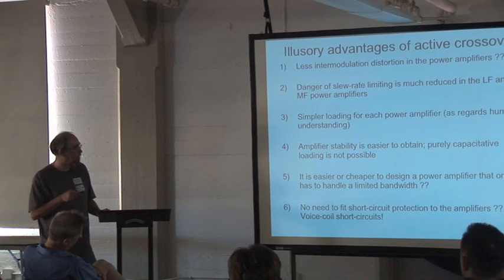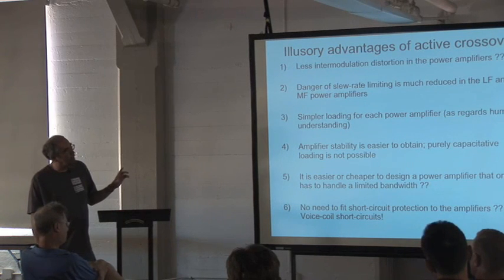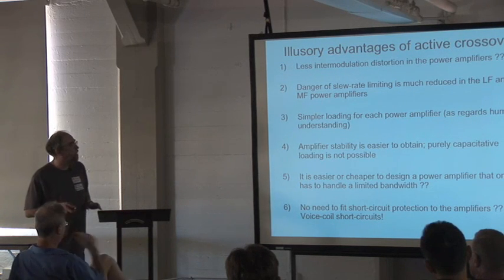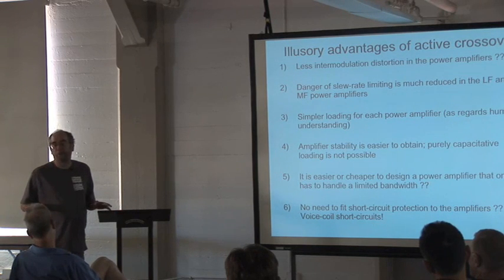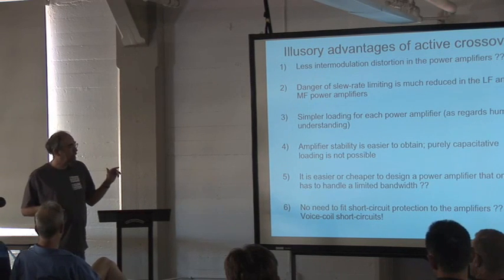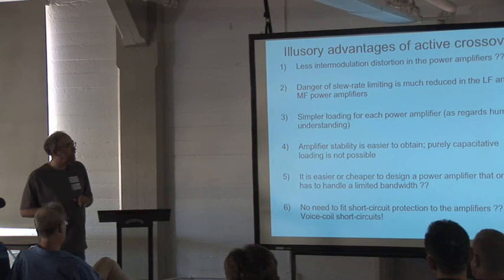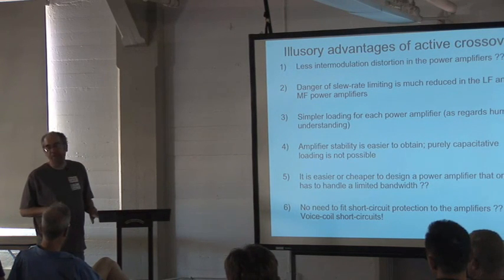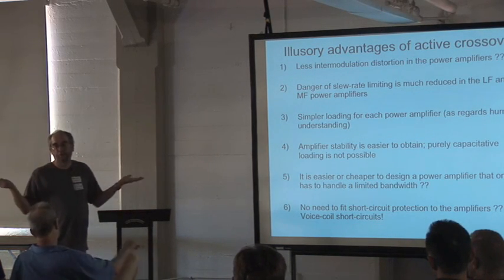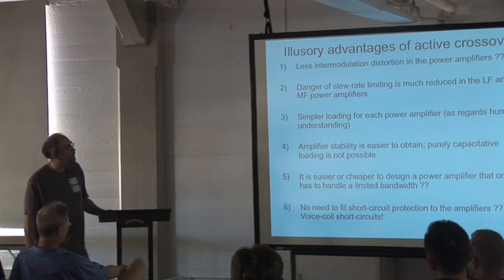Now, the last one's a very dodgy one indeed. People say you can save money. I'm talking here about a situation where you have your power amplifier actually built into the loudspeaker box, which is perhaps not a good idea, but I'll come to that later. And so they say, right, okay, there's no exposed terminals. You don't need to have short circuit protection on the amplifiers. And that will save you a few pennies until you get a voice coil that goes short circuit, and then everything catches fire. You've also got the problem, it makes it a bit iffy in the testing stage. You know, human beings make mistakes. So if you've got a power amplifier with no overload protection at all, a momentary short circuit while you're wiring it up and it's gone. So I always put short circuit protection on amplifiers.